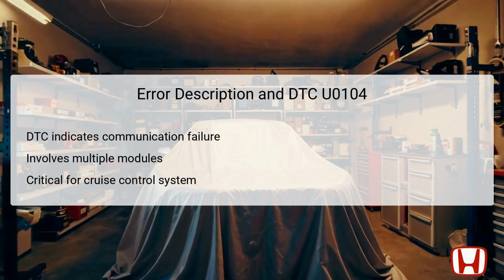Located in various sections of the vehicle, these modules rely on the Controller Area Network (CAN) for proper functioning. The ACC uses signals from these units to execute speed adjustments, and without proper communication, it may become non-functional. This highlights the importance of established connections and wiring integrity between these units to ensure dependable cruise control functionality.